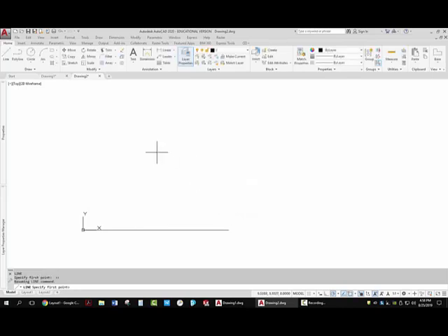What that means is that now if I hover over something here, you notice it's getting the endpoint. I have to be on the endpoint. If I left click, it's still going to snap to the endpoint. But I also have what's called tracking, which means I can hover over this and acquire the endpoint. And now when I move my cursor away, if I go directly above it, I get a tracking line. The space from the first line to the next line is supposed to be 0.75. I'm typing in 0.75, and now that distance from the first point to the point I just started is 0.75. This line is supposed to be 9.313 units long, so I'm going to do that.